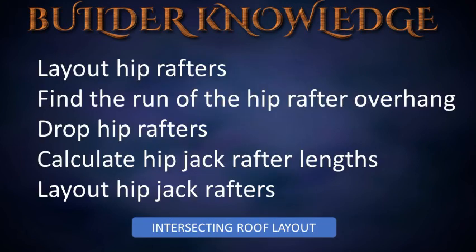Intersecting roof layout and framing installation procedures. Layout hip rafters. Square a line back from the end of the rafter stock and mark the center point.